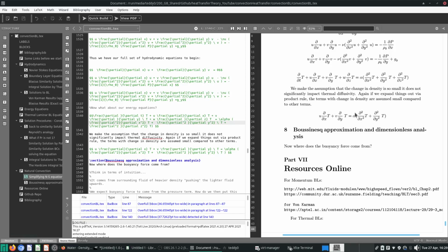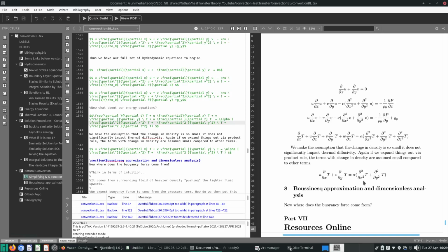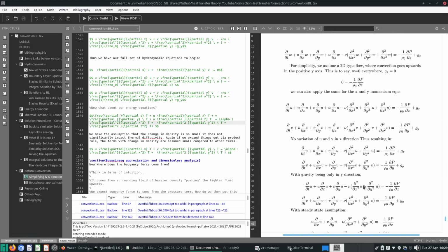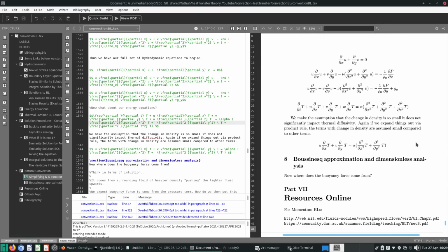So that's pretty standard. So earlier I talked about something called the Boussinesq approximation. Why do we need to talk about that? As with every boundary layer equation, we want to drop off more terms in the boundary layer. We know not all terms in the boundary layer equation are actually significant. So we'll do some scaling analysis to find out which terms we can drop further from our Navier-Stokes equations. So that's what we are doing here.